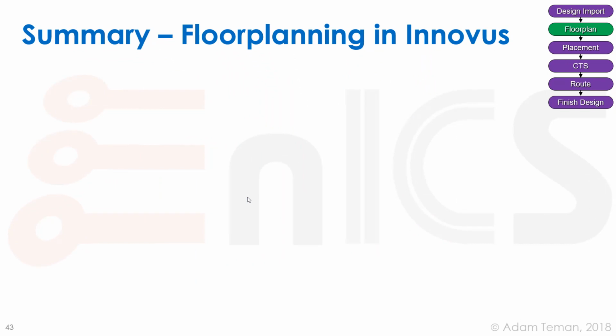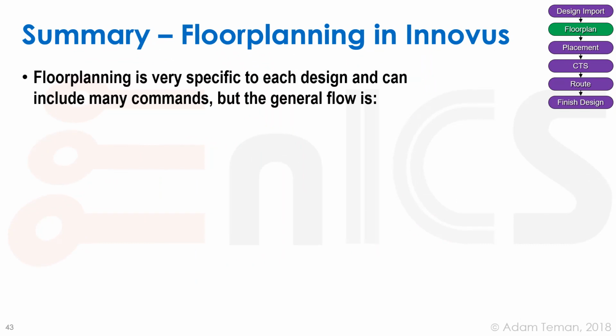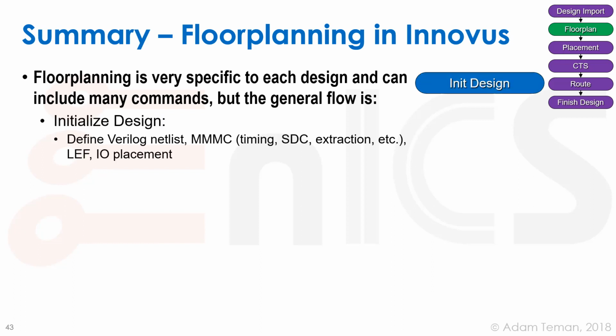So as a summary, let's see how we floor plan in our place and route tool. Floor planning is very specific to each design and can include many commands. You're going to have to always change this according to your specific design, but the general flow is we're going to first initialize our design, which means we're going to define all our inputs: our Verilog netlist, our MMMC, which includes the timing, SDC, extraction, etc., and what our LEF abstracts are,